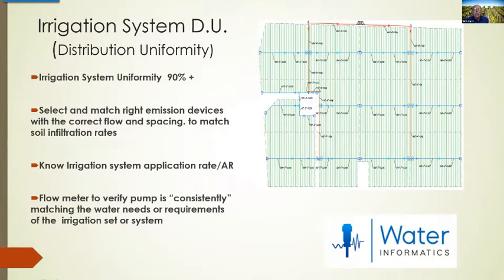As an example, on the west side of our valley, if I use dual line drip in an almond crop, and I put those hoses on the outside or off to both sides of the tree, 2 to 3 feet off, what'll happen is that soil, as I wet that area, pushes salt back to the center, and that causes some problems with the trees. Whereas if I used a fan jet and set it in the center of the tree row, it'll actually push the salts back out. So again, understanding your soils is critical.